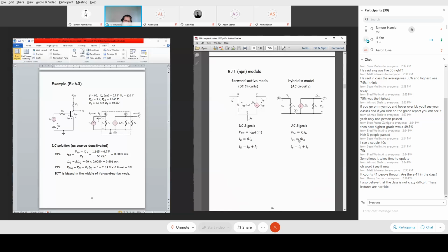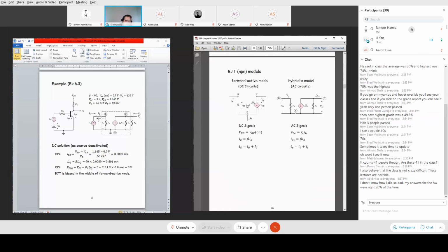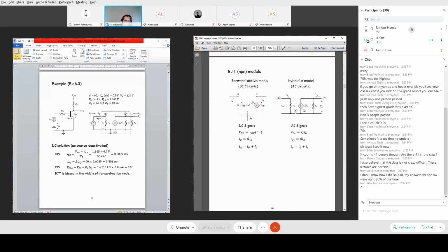That resistance R is renamed as R pi. So you can see this came in naturally from this diode model when you talk about the AC equivalent circuit. And this dependent current source has the same dependence as the previous one, because this dependence is for the full signal, so it's the same for the AC signal. The only modification is that this represents only part of the current IC, so I call it IC1.